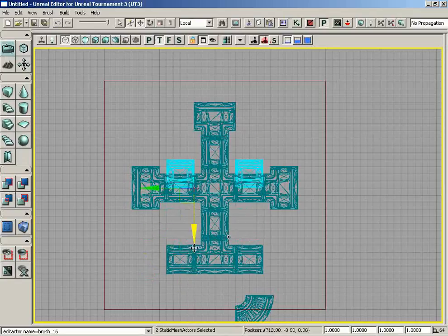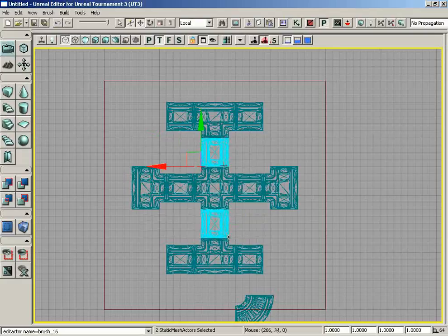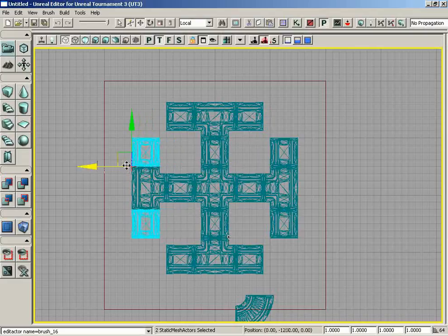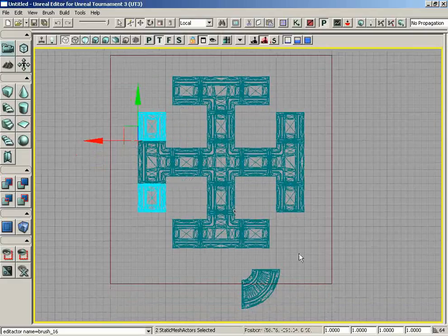And then now when I drag those out, I was holding the Alt key. As you can see, you just repeat the process over and hold Alt again. So release Alt, hold Alt, and drag out a second pair. That's right. Now one more time. Hold down Alt and drag to the right. Let go of Alt, hold it back down, and now drag off to the left. And really all we're missing at this point are these corner sections.